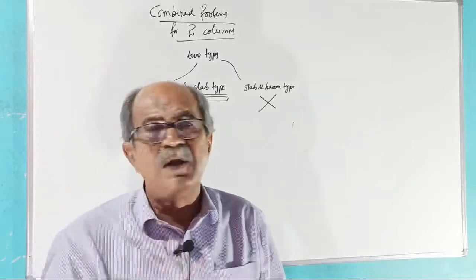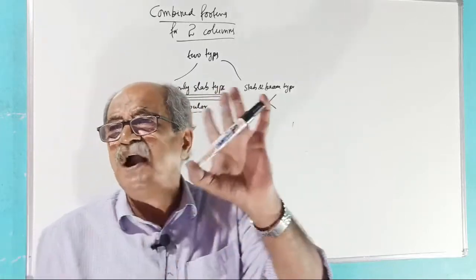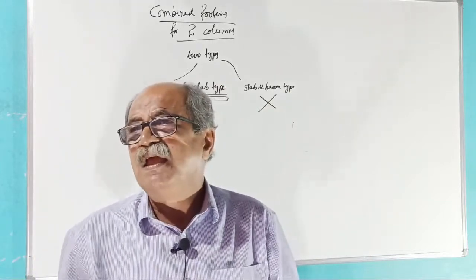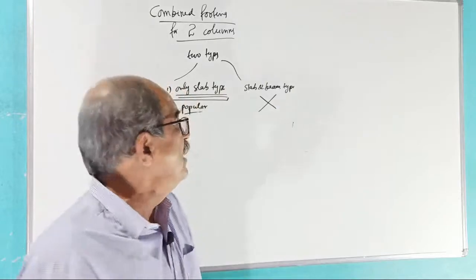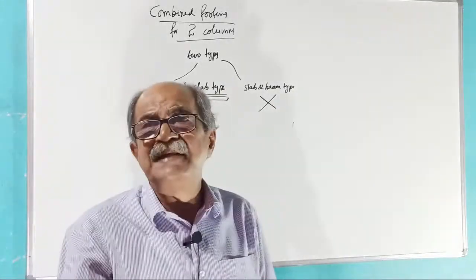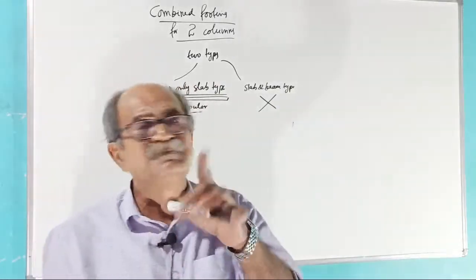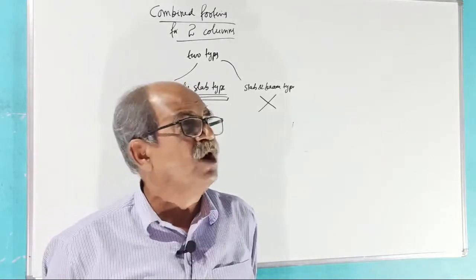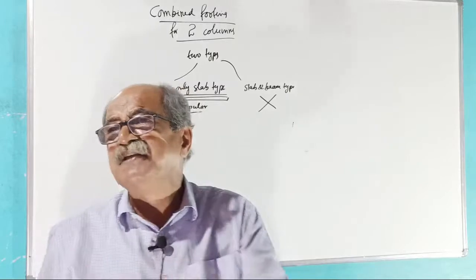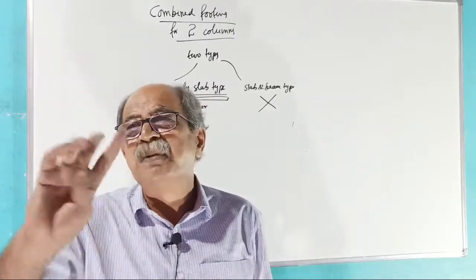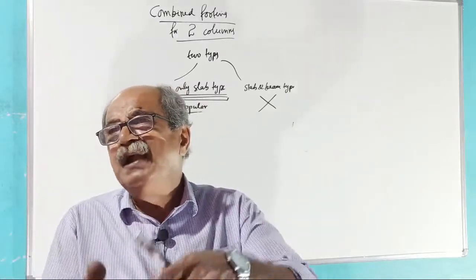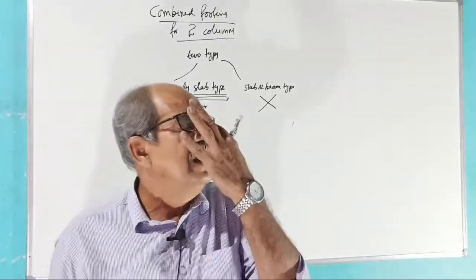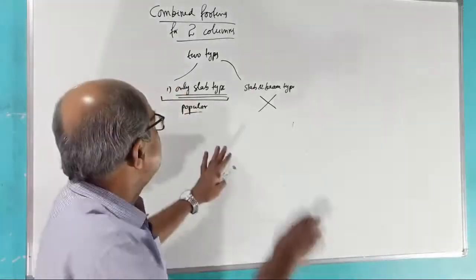So to avoid that, nowadays wherever you go, they provide isolated footing only, and combined footing also only slab. I will tell the sketch here. Beam and slab type is outdated. Still I will explain. In the theory books, even for raft footing, you can see beam and slab type. Completely outdated. They will provide only slab. If required, the thickness will be increased. Then all those will be discussed in the design principles.